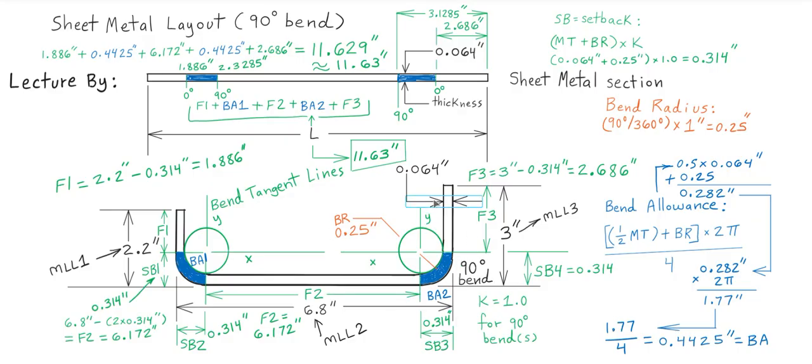So we have our depth in here, and we place our rivets, and then you have a structurally sound part. You might have an offset to place a rounded edge or chamfer here, and that would be your APU mount. So in accordance with the structural repair manual and the shop drawing, you'd manufacture from this unbent length.